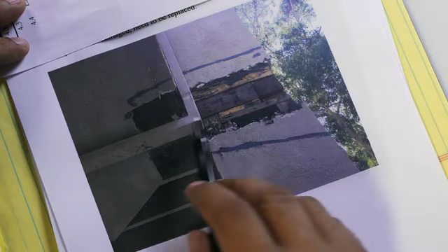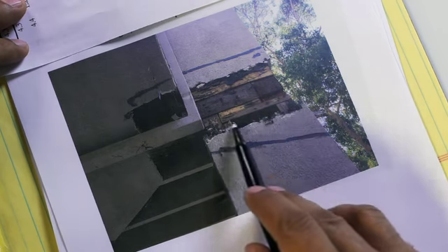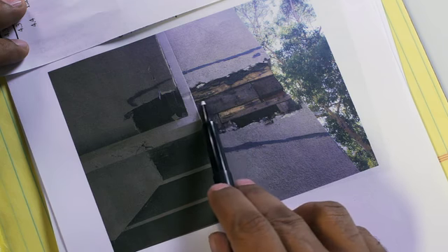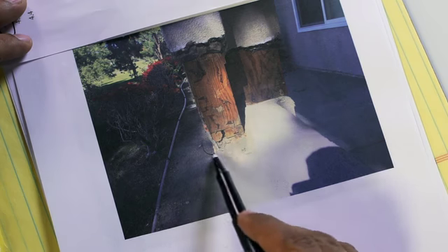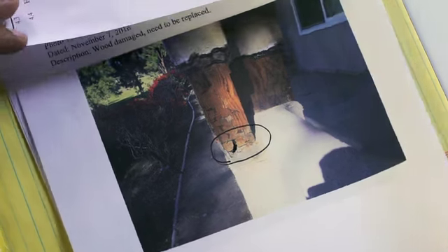And I want to show you an example of a couple of inspections that we've done recently of exactly what happens. And I'm going to try to hide the name of the property, but here's an example. This is on some balcony decks. And what we've done is we've taken the stucco away and opened up these decks in order to look at the condition of the wood. And you can see right in here the termite infestation where the wood has been completely eaten. You can see over here the base of the post is completely eaten. You can see the holes in the wood.